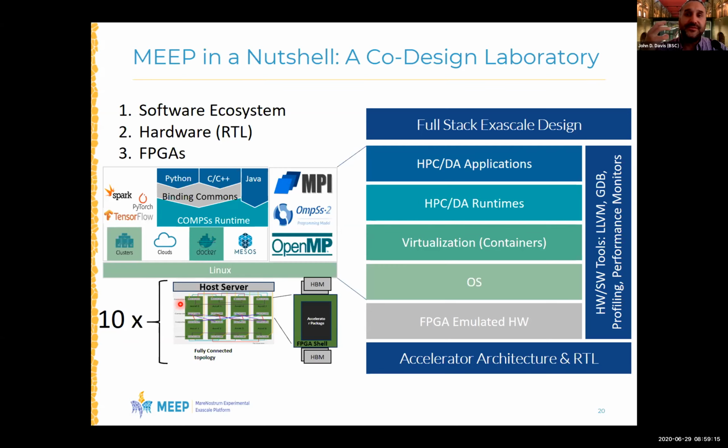So you can download the RTL, Chisel, BlueSpec, System Verilog, what have you, and then build the system from there. If we're mapping it to an FPGA, it's just going through the process of synthesis, place, and route. If you're doing it for an ASIC, then obviously there's a whole physical design backend that you have to do. So from that perspective, you have capabilities to map to that level. Hopefully that answers that question.